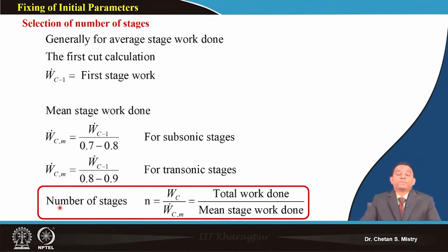Let me say, the HP compressor is most important. If you recall, in the last lectures we discussed the HP compressor, that it is the heart of the engine. And a few percentage loss in efficiency will be reflected as a great reduction in fuel economy. At the same time it may be subject to formation of stall or failure of the engine because of surge. That's the reason people are very careful when designing the HP compressor. So let's discuss how we decide the number of stages.